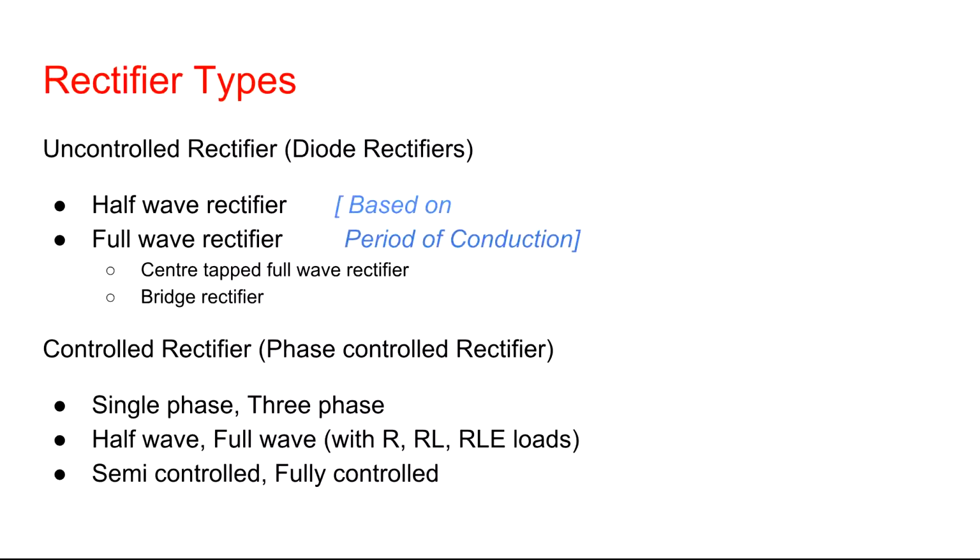Now I would like to add one important point. The half wave rectifier circuit in real life, for commercial purposes, we never use. This is just for theory purposes, for understanding to proceed further to how the bridge rectifier, the full wave rectifier, or SCR based rectifiers work. Okay, now get into the topic.